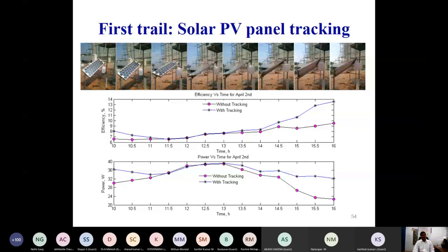That means efficiency as well as output is more at solar noon. But the main issue is the sunrise time as well as the sunset time. These two issues have been addressed by adopting a small tracking mechanism in the PV panel. After that, in the second attempt, the second level, a linear concentrating collector was integrated with the solar PV panel, and I will show the versions of this linear solar concentrating collector and how it runs with reference to this mathematical model.